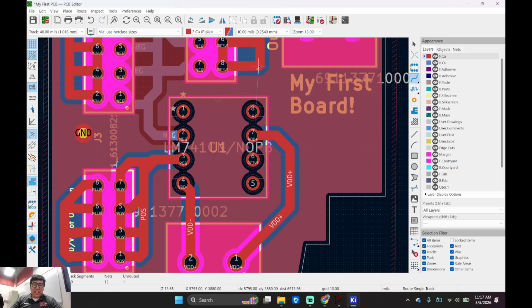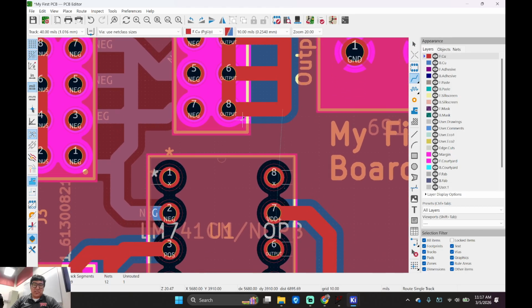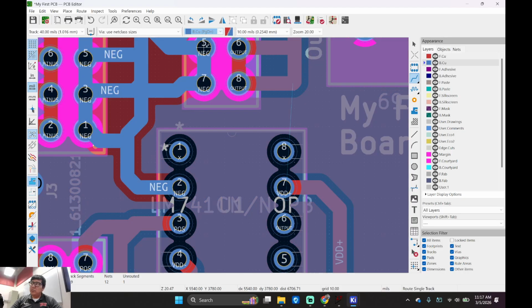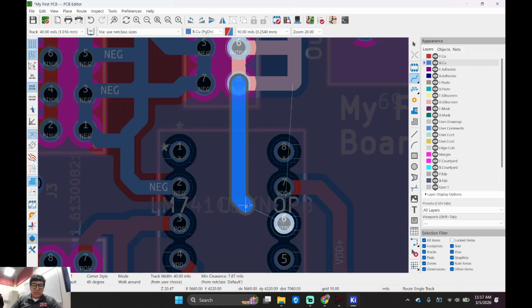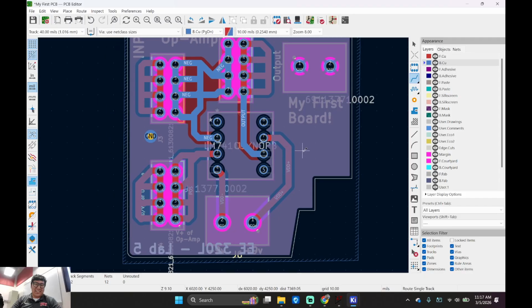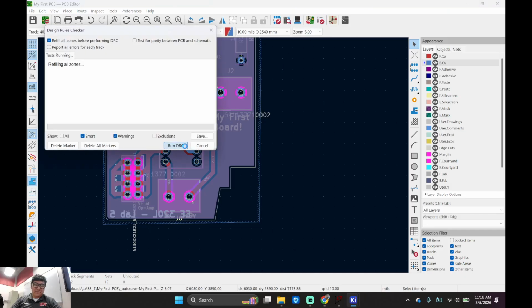Is there any other pins? Oh yeah. You see this output right here? Let's go underground. Okay, I'm gonna do the blue pencil, right? Blue pencil, correct? Go here. Boom. Boom. Boom. Did we fix this student circuit? Right? I don't know. Let's just DRC it. Well, save it, right? Let's DRC it. Or not, design rule check. Where is it? Right here. Design rules check.